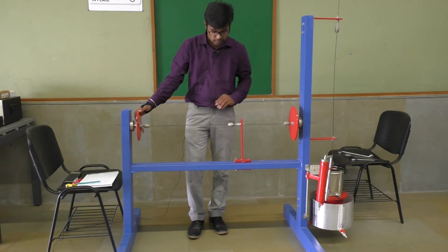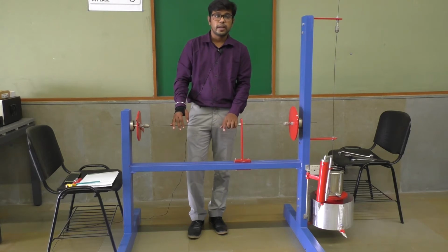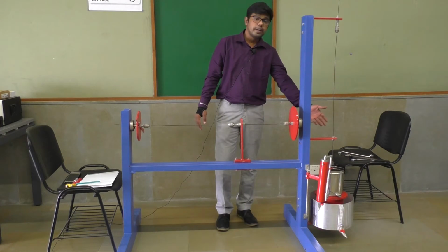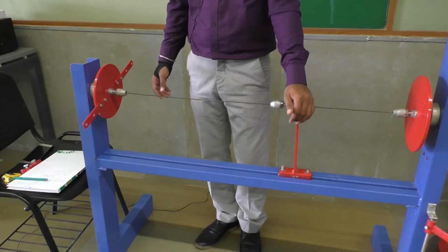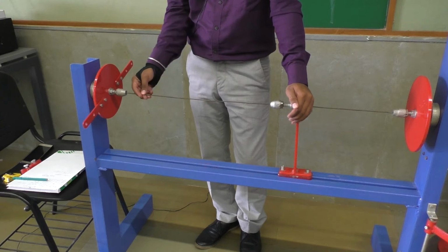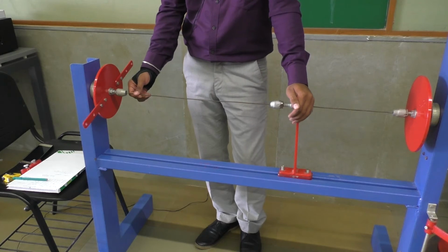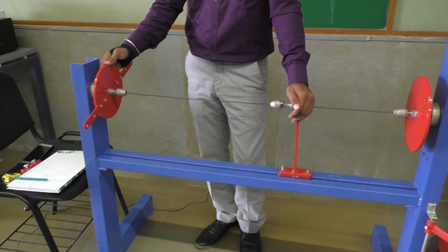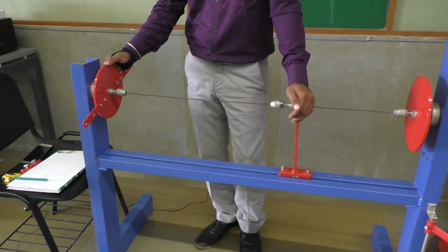In case of a single rotor system, we have to clamp it from here, so these two rotors would behave like individual systems. And this apparatus over here is for damped torsional vibration of a single rotor system. Presently, we'll be doing the single rotor system. This is a shaft made of spring steel and the diameter of the shaft is 3 mm. The rotor diameter is 0.19 meter and its weight is 2.15 kgs.